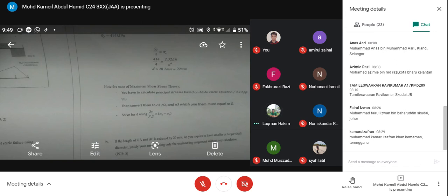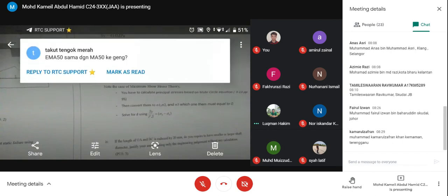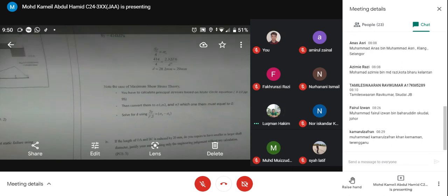If we just reduce the length, what is the size requirement for the shaft? It should actually be able to use a smaller one, because the moment is getting smaller. So you can use a smaller shaft, because the moment it produces is going to be smaller.